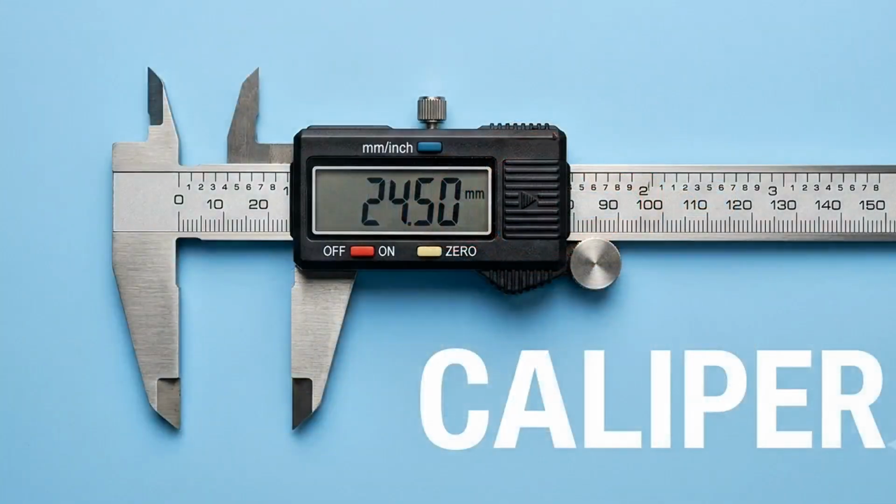A caliper is used to measure the thickness, inside diameter, outside diameter, and depth of objects with high precision. It is widely used by engineers, machinists, plumbers, and metal fabricators. Digital calipers provide measurements instantly on a display, while vernier calipers require manual reading. Accurate caliper measurements ensure that parts fit together correctly.